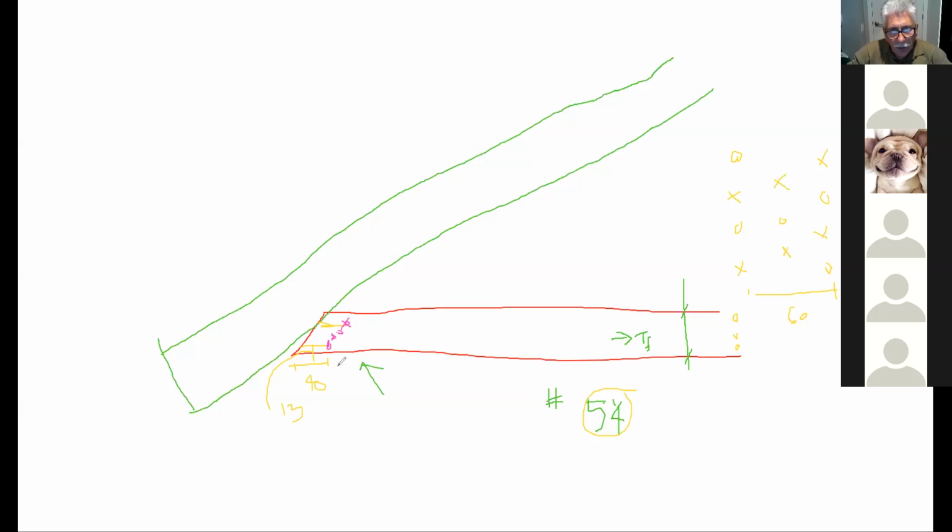Then all you're going to be doing is moving over by another 60 millimeters, you're simply going to add another row, right? And then you're going to move over by another 60 millimeters, and you're going to add another row. And then in between, you're going to put your 3 additional nails. So far, so good? So therefore, that means that up to here, every time, where did I put my 60? Here's my 60, right? So every time I add a row, in your case, you end up getting 1, 2, 3, 4, 5, 6, 7, 8 nails, right?